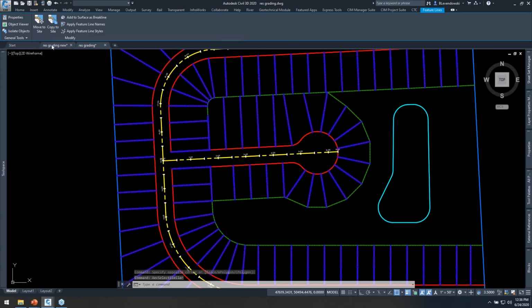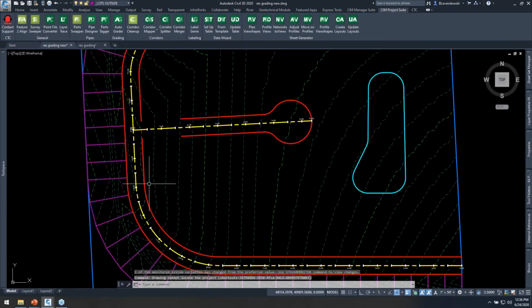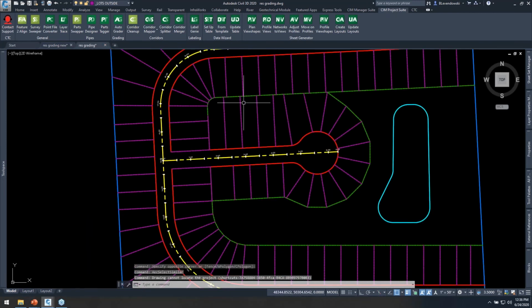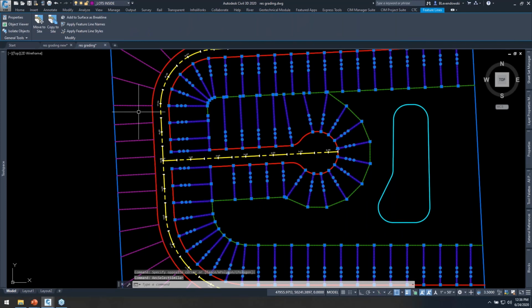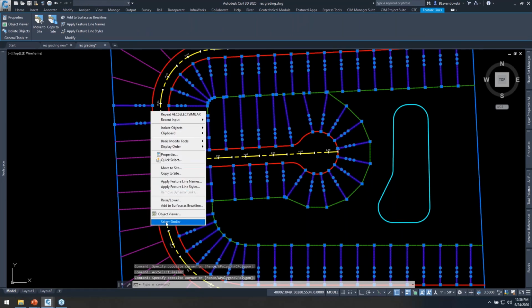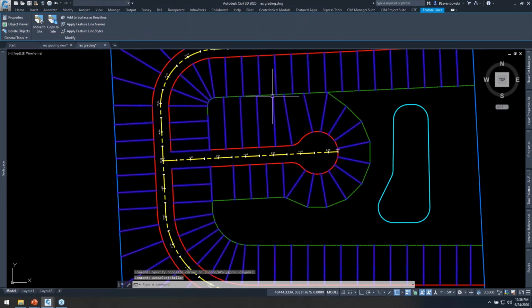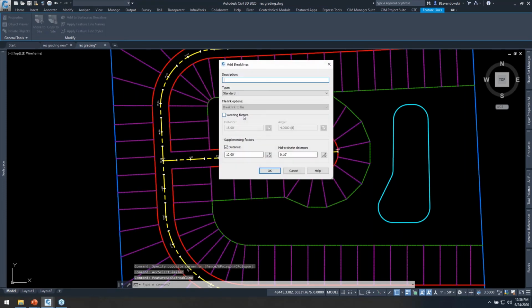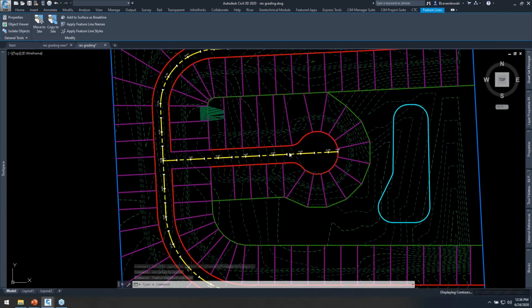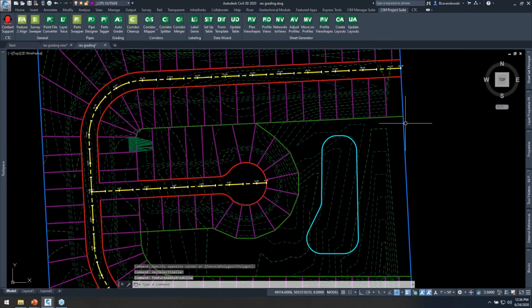You had seen me show it in this other scenario. Like I said, we're working through final kinks, and something with this grade existing scenario is not putting those in the surface. Obviously, we'll button that up before we release this. So I'll grab all those lot lines. I can simply add them into the proposed surface. Okay, and then we see all that grading.